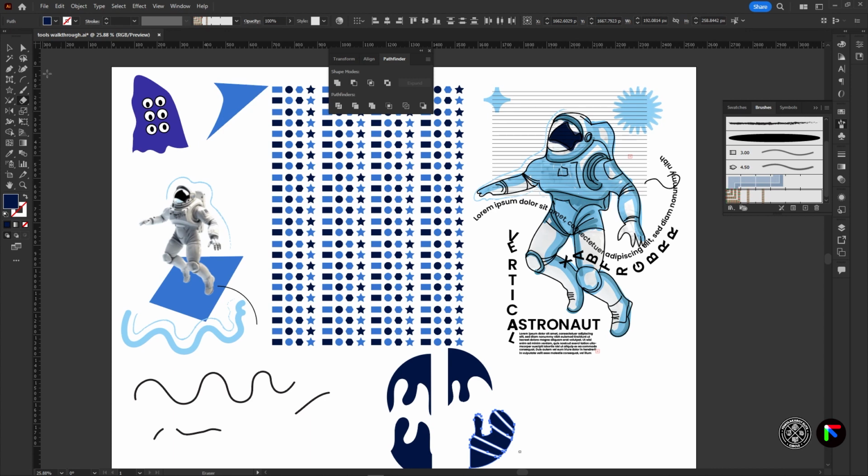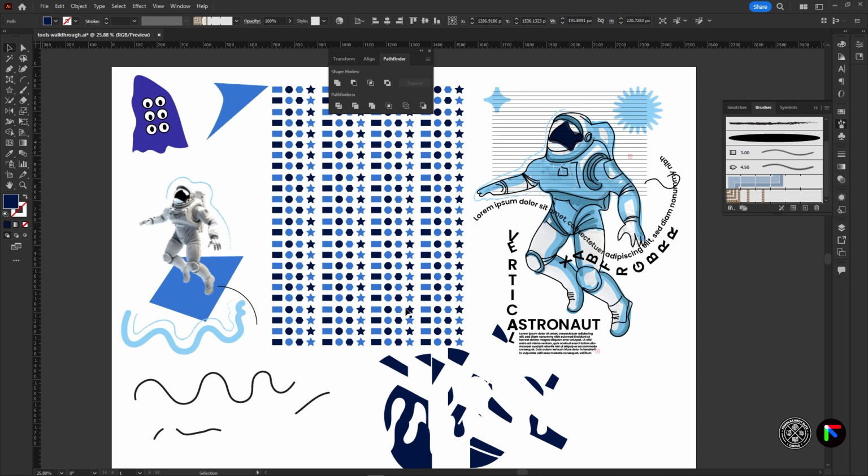So let me just select this and this and this, and then pick my eraser tool and then begin to do this over the eraser tool. Make sure you get to the end of the point, like so. And then you can also, after erasing, pick each member and separate like so. So that's what the eraser tool does. The cutting tools in that regard, that's what they do.